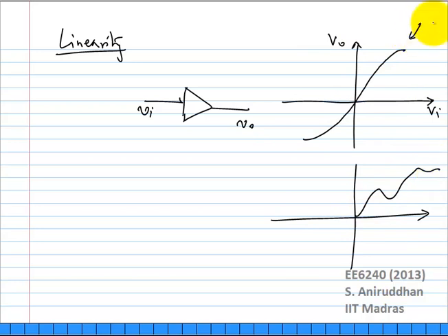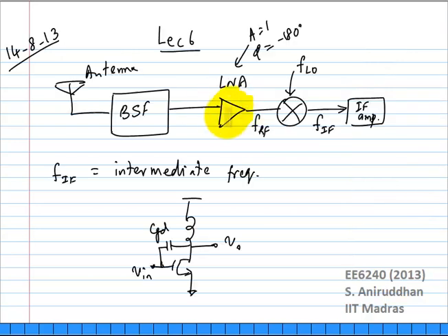This case is a soft nonlinearity where it looks very linear for small signals. As the signal keeps getting larger and larger, it seems like it is saturating in some form. Okay. So what happens if you actually put in a lot of gain up front here in the LNA? What will happen is the signal will saturate, so the mixer needs to be able to support even larger input amplitudes. Okay, that could be a problem. We are going to look at this systematically in the next few classes, but that could be a problem. You don't want to put too much gain up front.